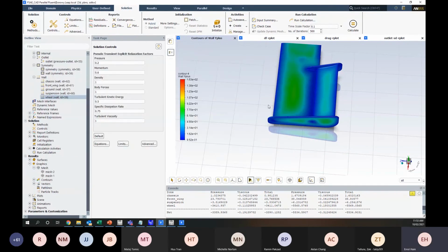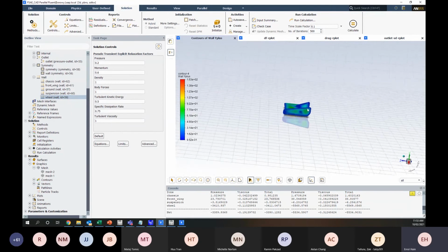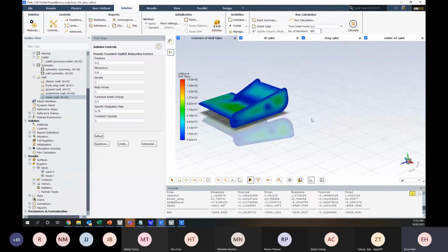Okay. All right, what else can we show quickly before we end the session today, even though the model might not necessarily be 100% correct? So Stefano, good question. I assume because we saw the inflation layer not capturing the boundary layer with enough elements that this could be causing residuals not decreasing smoothly. This is an annoying thing about CFD. That's not necessarily correct. So not resolving the domain with enough elements is not necessarily a problem for convergence behavior, because if you're not resolving with enough elements, it's actually an easier solution.